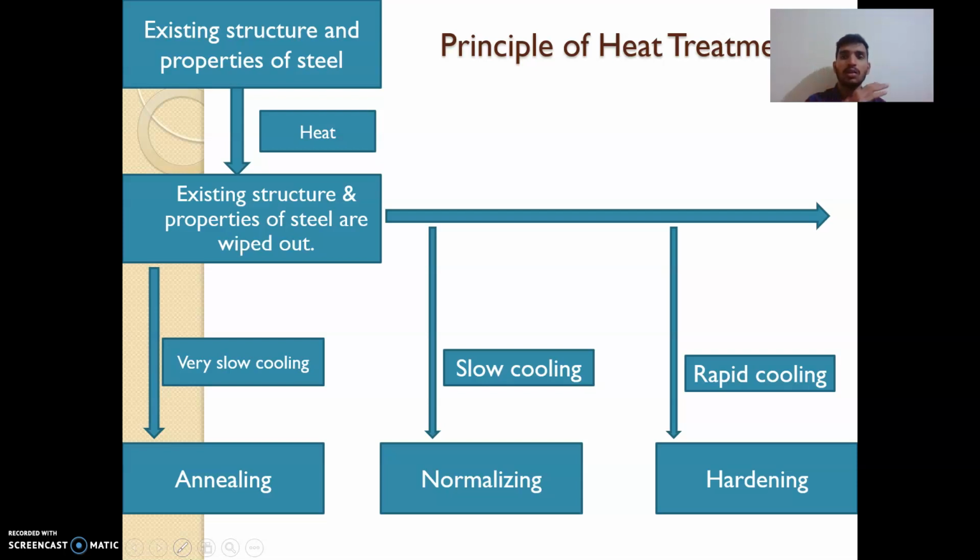Charcoal is not good, it increases the carbon content, and with the increase of carbon, corrosion takes place. By the tempering process, the internal stresses developed after the hardening process are removed, it improves the grain size, and the metal can be used for a long period of time.